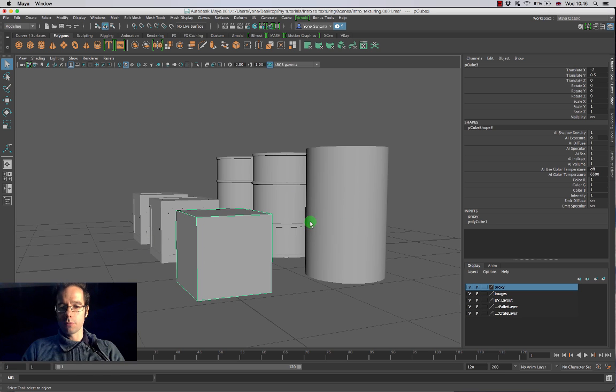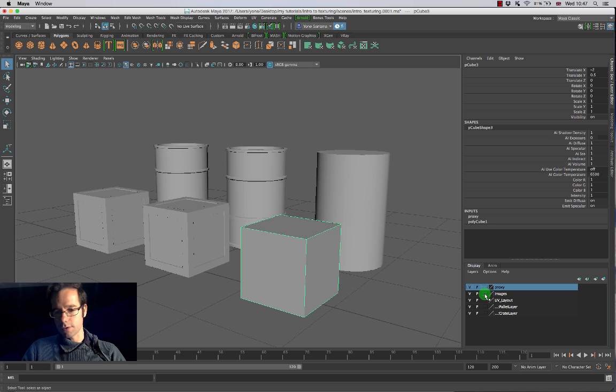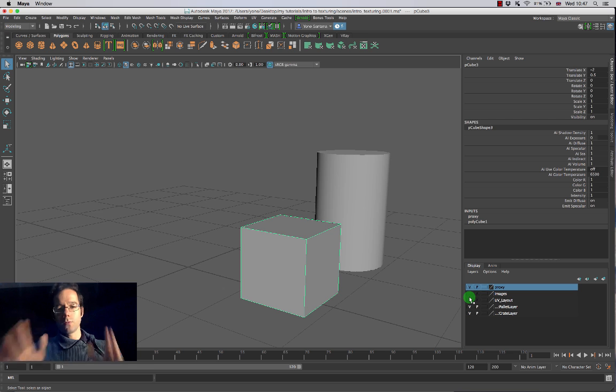So you can select objects inside your viewport and add them into a layer, and then you can turn the visibility of this layer on and off, and you can arrange your scenes as well. Another cool feature is that you can also make your layers non-selectable, so you can lock them so that you have objects that you can't touch inside of your scene, by pressing this little button next to the visibility button over here. So what I'm going to do, this one over here for transparency and reference over there. Okay, so what I'm going to do is just hide away some of these,